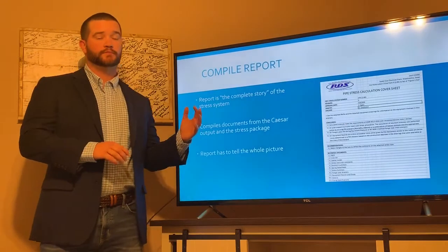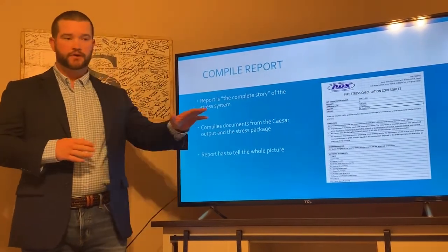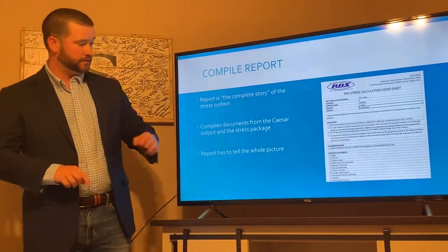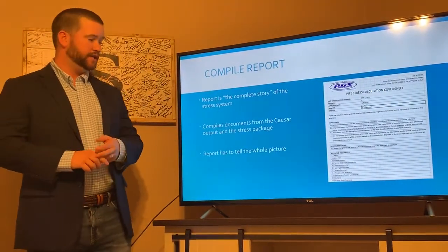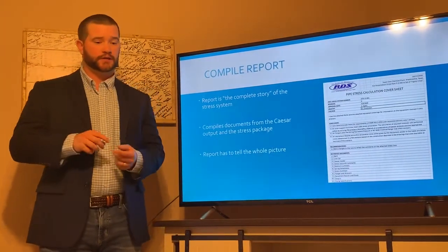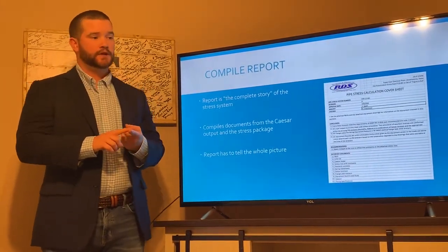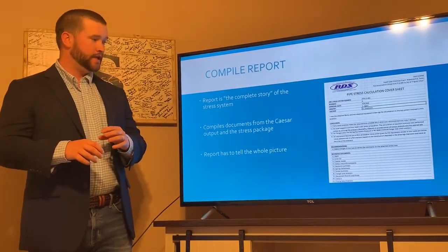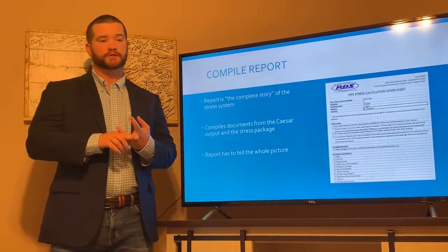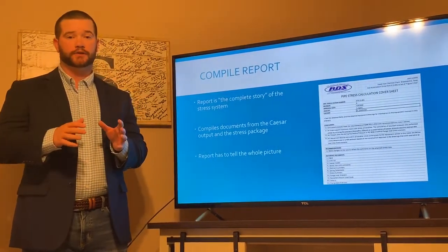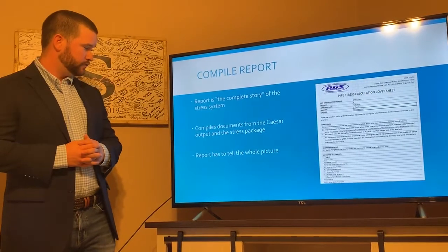You have to assume that the person reading your report has no knowledge of this system. So you're going to tell them how you built your model, and that's what your ISOs and your P&IDs are for. And then you're going to print out your results, which are things like a stress report that tells where the highest stress point is in each load case, and a restraint report, which tells you that none of these supports are carrying too great of a load for what they're meant for.